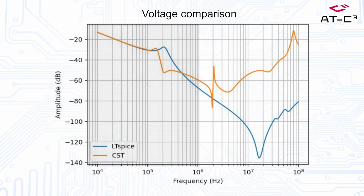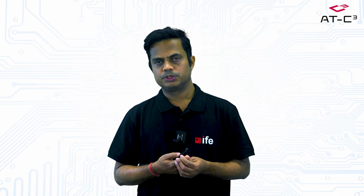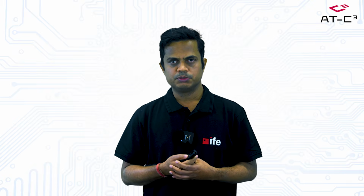Now let's compare the filter performance. The blue one is the SPICE level or network level simulation, and the orange one is the full wave simulation. Again, we can see there is a good correlation between SPICE and the full wave simulation until around 1 megahertz. After that, there is a huge difference between the full wave simulation and the SPICE simulation. This helps us understand when to use the network simulation and when to use the field level simulation.